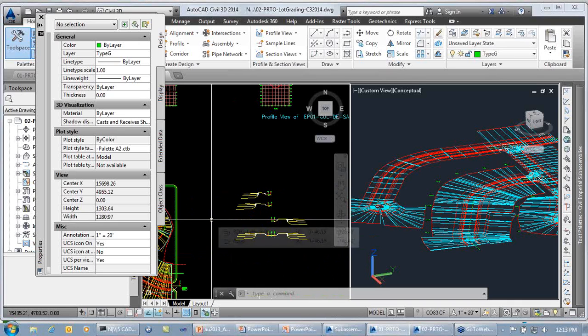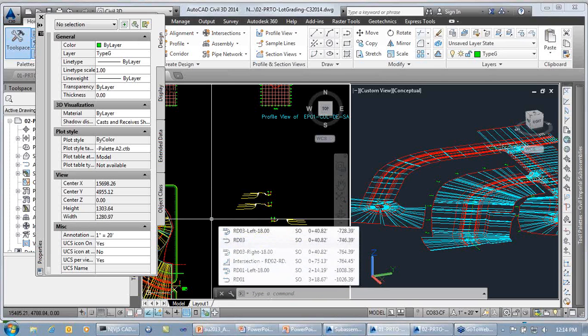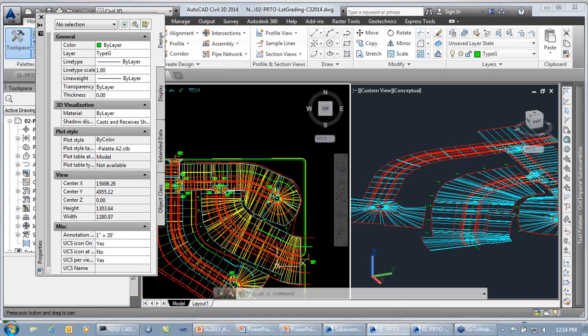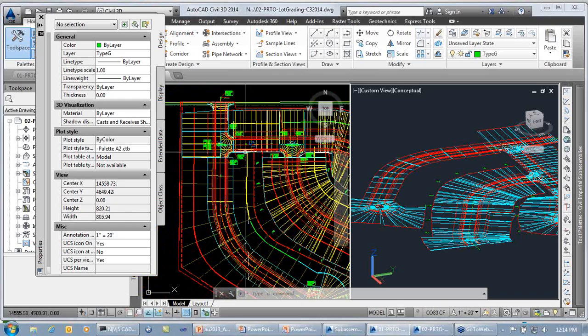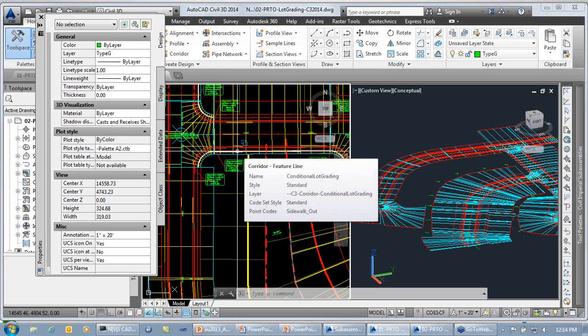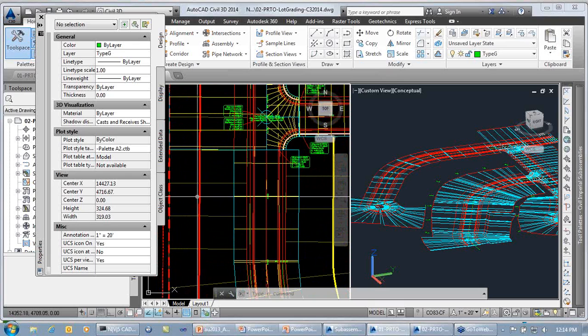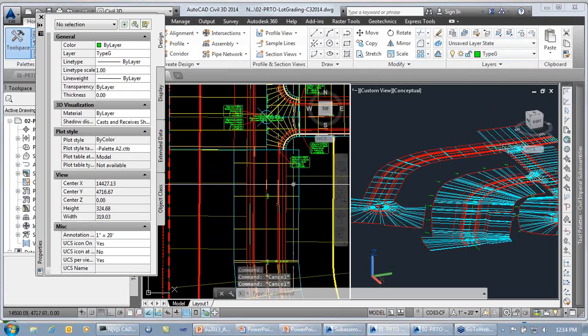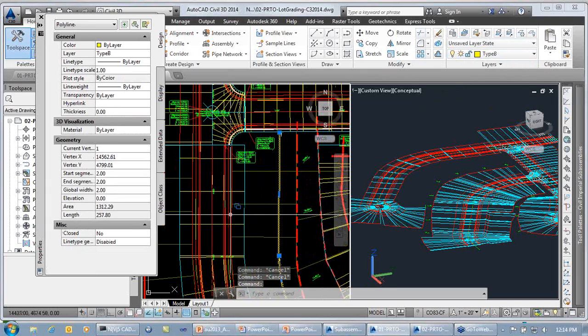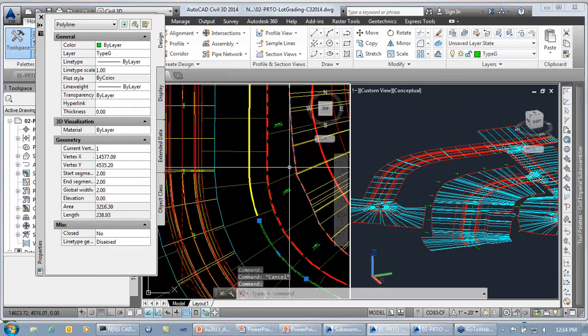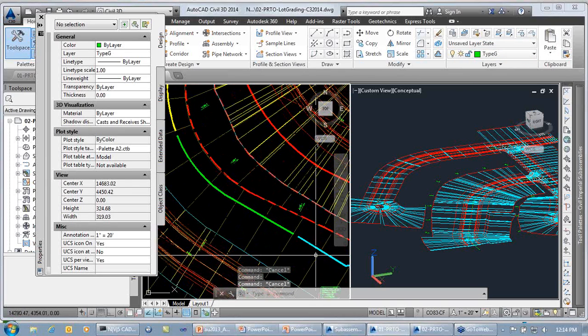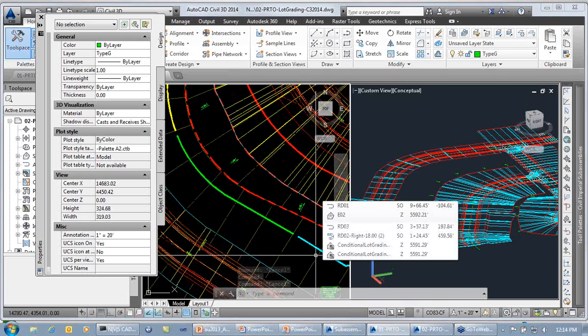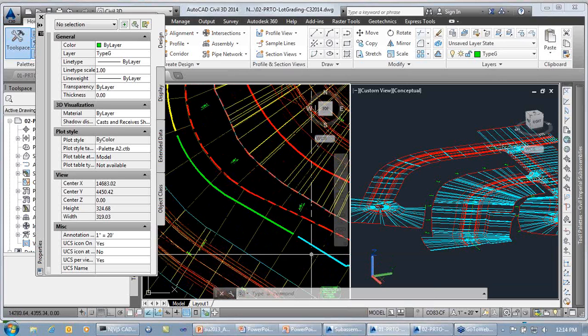So for the model now, we have all of our different regions, and in the regions we already looked at the white polylines I've drawn for the don't grade lots here, target. I've then also created 4 different layers for the different types. So I've got one layer that is red, that's going to be my type A. I've got another layer that's yellow, which are my type B. And I've got a green one that's type G for the garden, and then the cyan one that's the walkouts. And I've actually used just the primary AutoCAD colors 1, 2, 3, 4, so I know quickly at a glance which type I'm looking at.